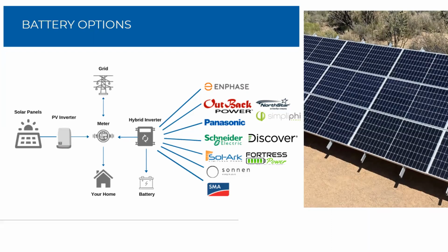Okay, next question is, do you have an estimate for how much a smart electrical panel like the Span or the Lumen will affect installation time when compared to rewiring a sub panel? Great question. Also, I want to say the Lumen takes 90 minutes to install. So take that with a grain of salt on how long you think it would take to rewire a sub panel. I think that would take way longer. The sub panel takes way longer.